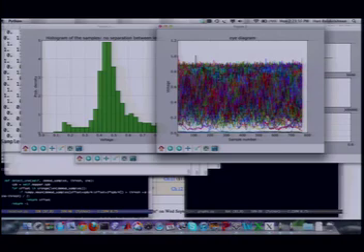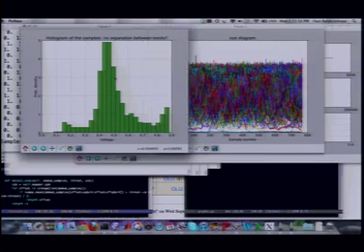This is a picture that will become your best friend, or maybe your worst enemy. This is called an eye diagram. And it looks completely messed up. So I'm going to show you what that is, and we're going to talk about it. This noise was too high. That's shown in this picture, where we ended up with enough variation that we couldn't distinguish between zeros and ones. We sent something which had a little bit of zeros in the beginning, and then the entire one distribution was spread between 0.1 volts and 0.9 volts. The variance is extremely high.